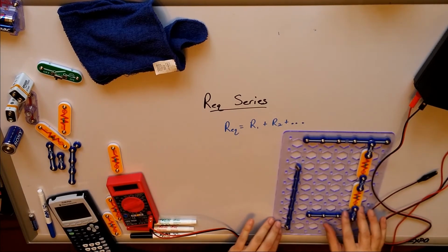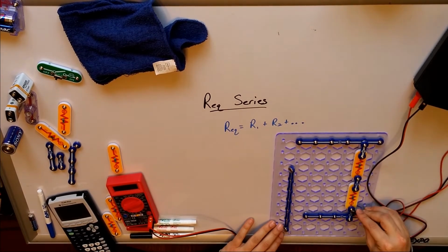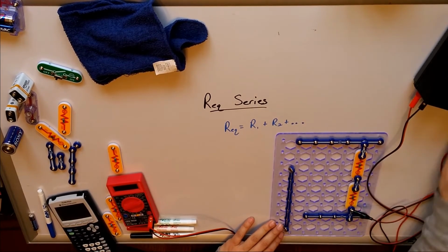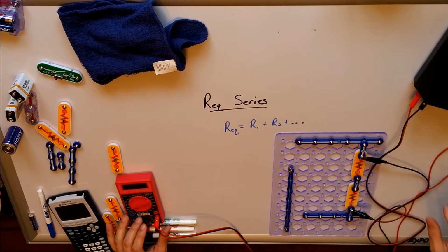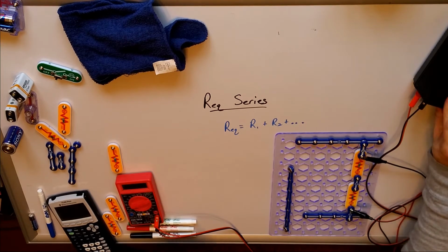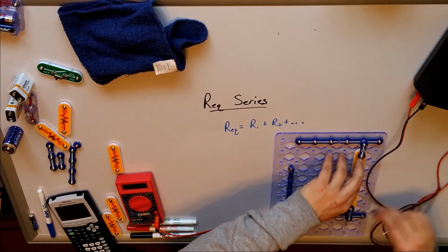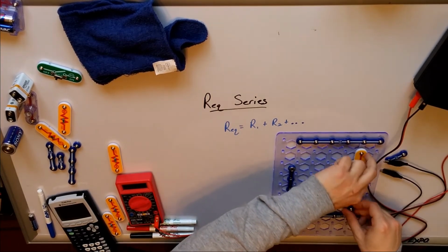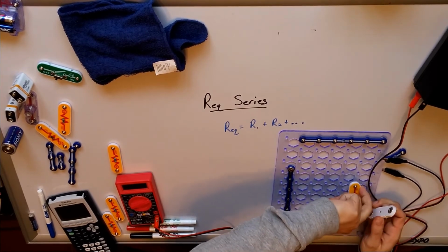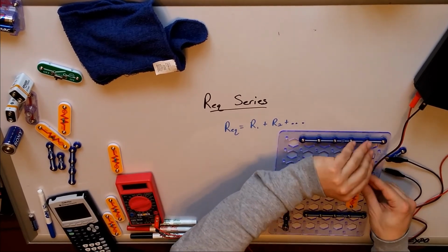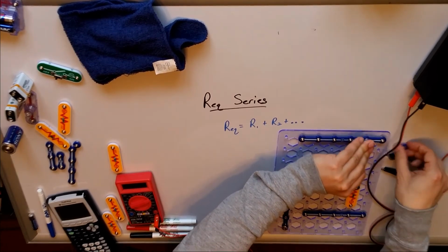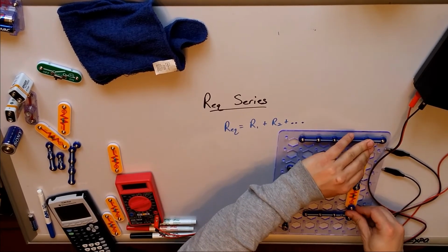One final thing that I want to point out is, and I've mentioned it before, that order doesn't matter. It doesn't matter that I've got the 1,000 ohm first or the 5,100. If I turn this on, I get 482 microamp. If I switch these out, I might get something slightly different because I may have adjusted some of the electrical connections ever so slightly.